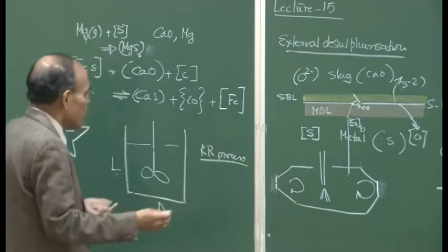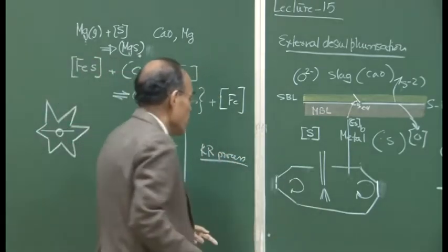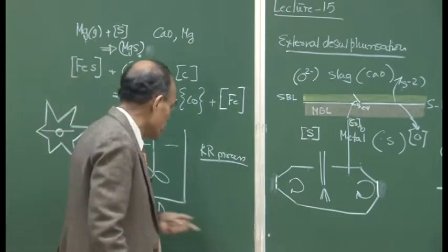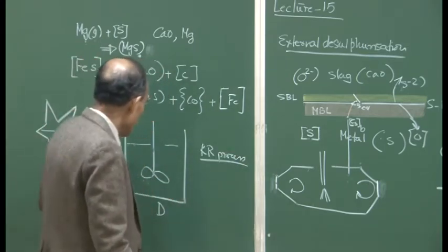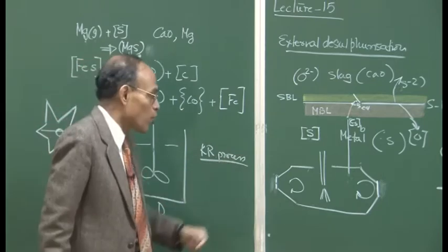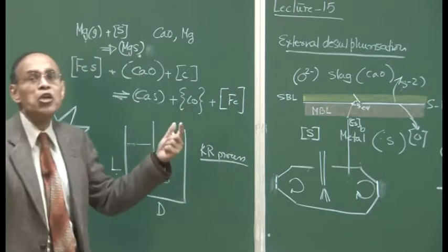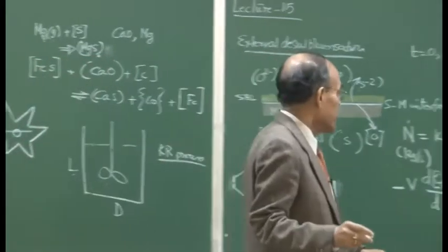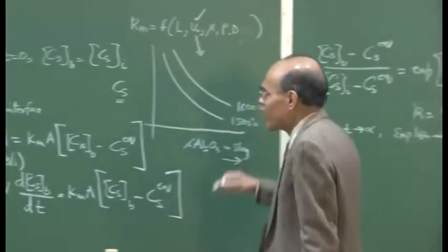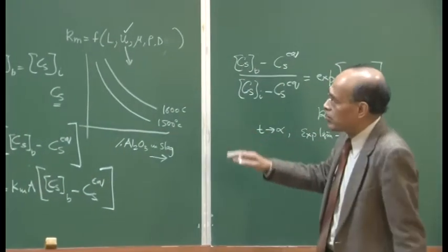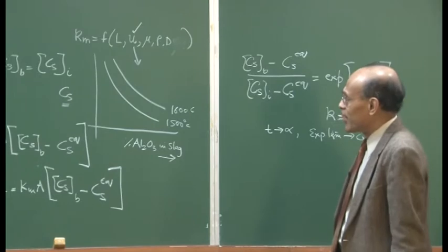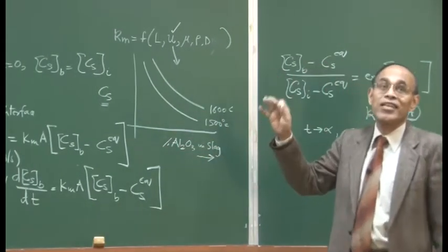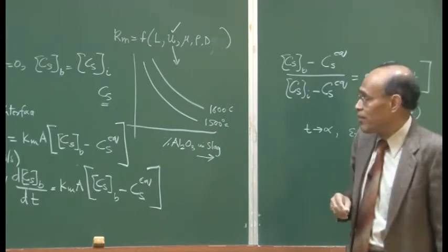But this is a very large volume, and ladles are not that big. So, you have the option to use both ladle and torpedo desulphurization vessels, and they are equally popular in the steel industries. I think I have given you enough idea about the thermodynamics and kinetics of external desulphurization, and these fundamentals are going to be useful when we study the actual steelmaking process.